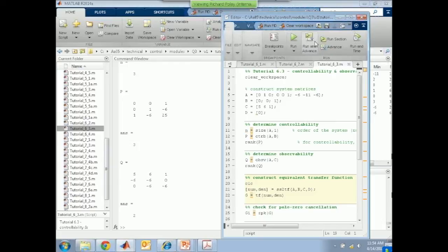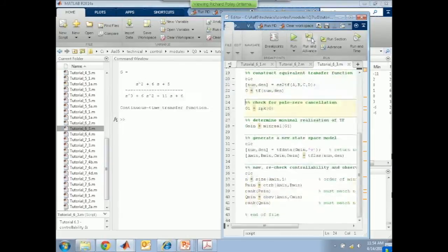Now, in an attempt to find out why, what I'm going to do next is to look at the transfer function representation of this system. So I'm converting the SS to TF using this script to convert to a transfer function description, and then TF constructs G, the transfer function, from it. So let's look at that. Simply this. Okay, nothing obvious so far. It's a third-order system with 2 zeros in it.